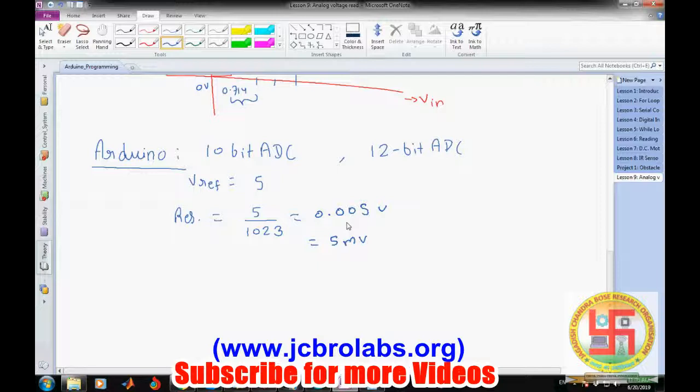So we have to go through the specifics of the sensor which we are going to interface with the Arduino, in which range that particular sensor gives the output. If the changes are within 5 millivolt, then obviously our microcontroller program will not be able to detect it. So at the analog part, we need to add some kind of amplifier so that this change comes out in the range of 0 to 5. That is a different concept, the amplifier, and that is a part of analog signal processing. So you must take care when you connect a specific sensor to the microcontroller.